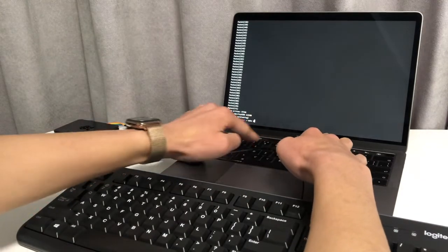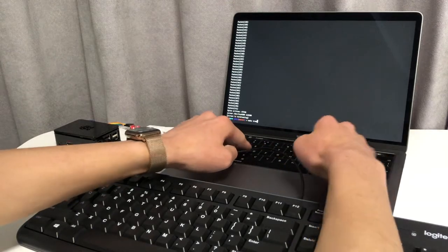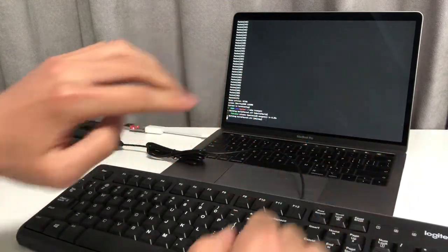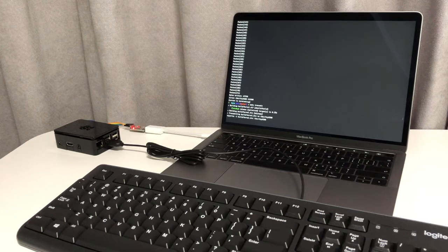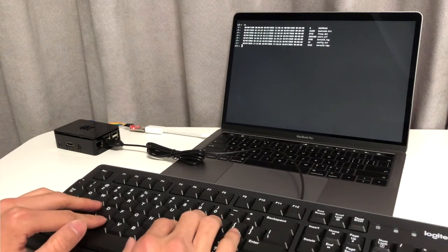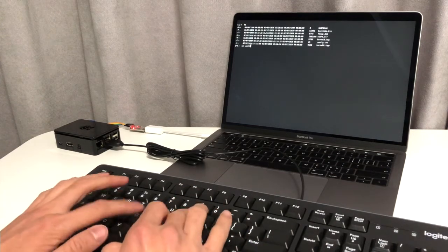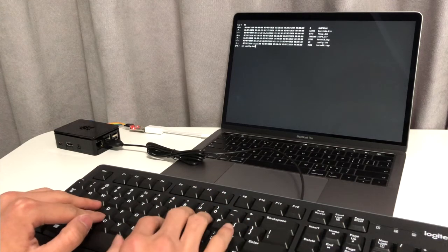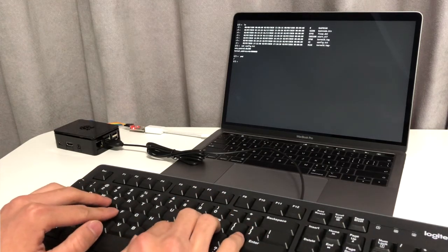So firstly, I type make transmit to transmit the pre-built kernel to the Raspberry Pi. The transmit has finished, and I will type commands like list, pwd, cat, and echo.